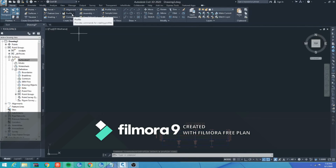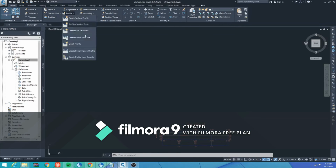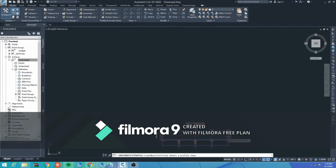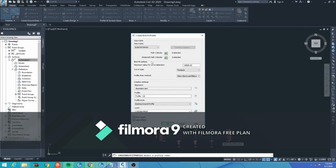We can also create a best fit profile by clicking on the profile, Create Best Fit Profile, hit enter. Surface profile. Everything looks good. I'm going to hit OK.